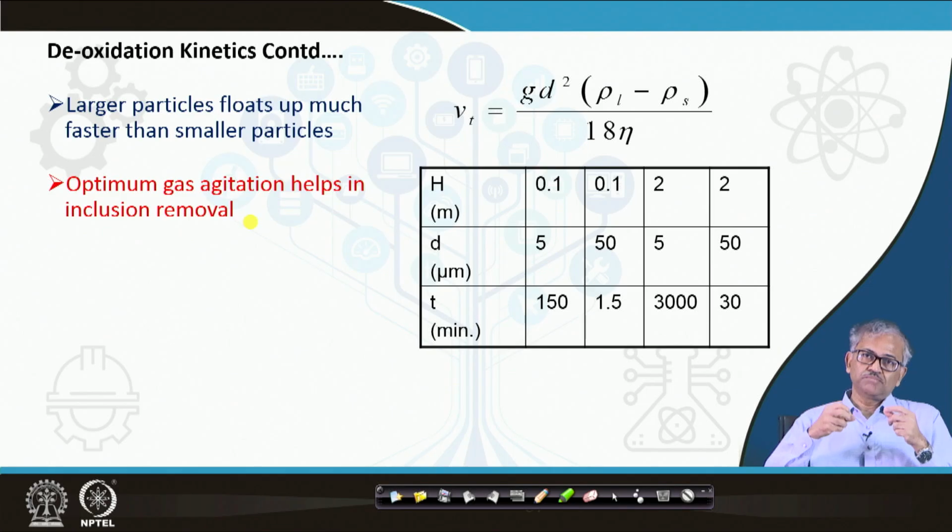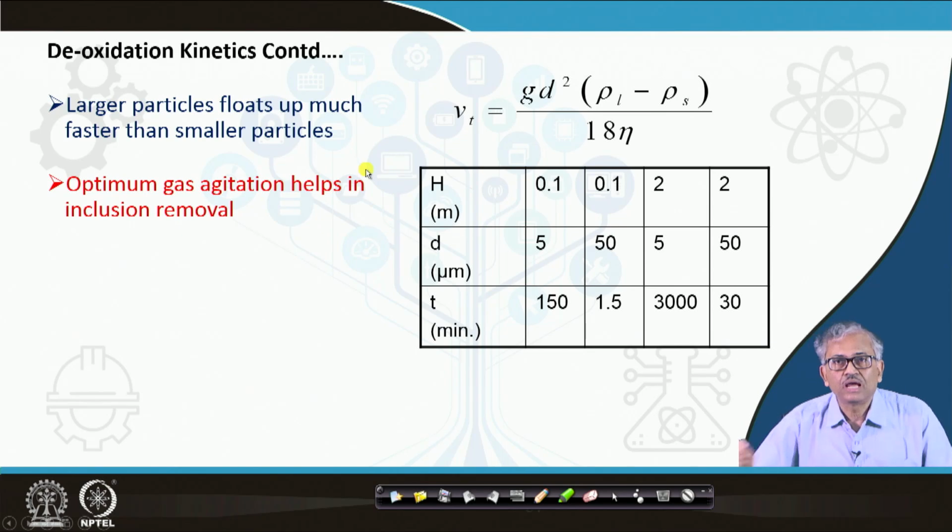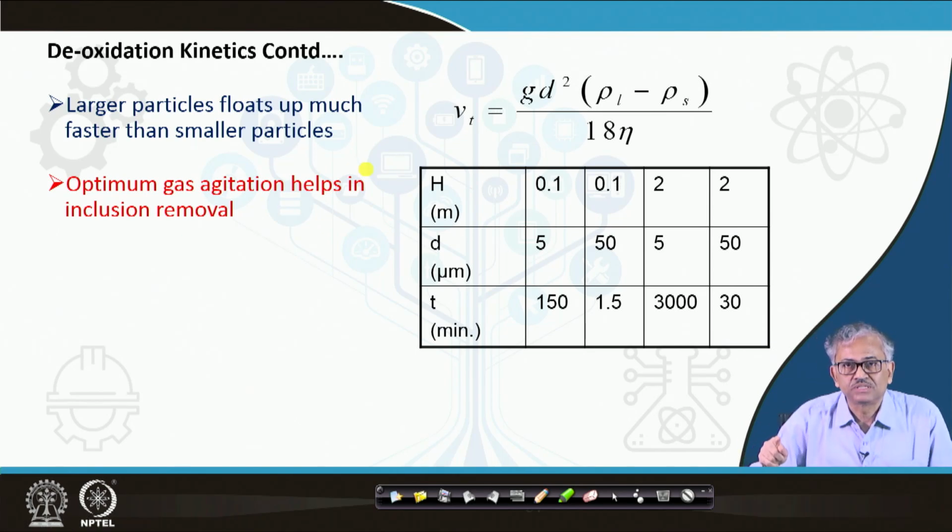So most of the time the inclusions will be entrained in the moving liquid and follow its streamlines. The impurity will move with the liquid and reach the surface.